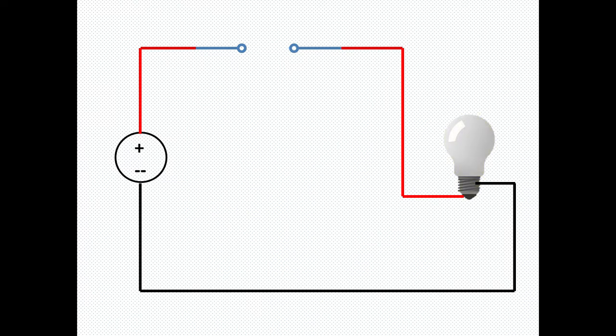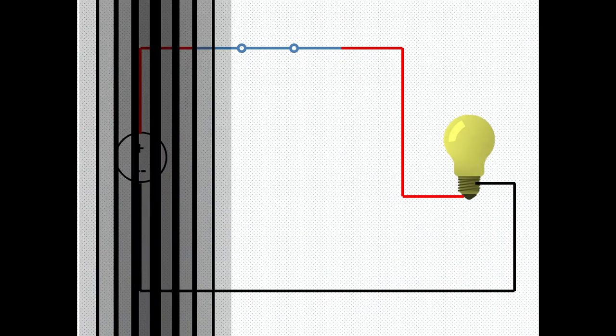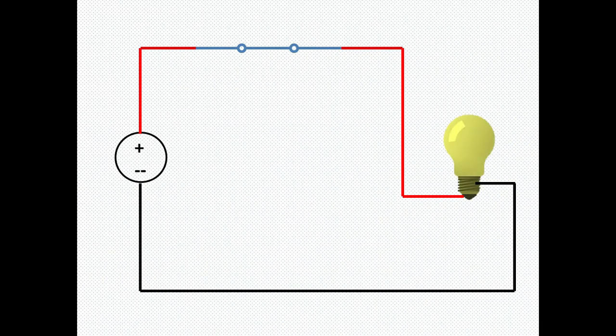At this speed of transition, one can clearly differentiate between the on state and the off state of the load. Let us increase the speed of the switching. As you can see, the lamp is also following the switching speed and it is turning on and off accordingly. At this stage also, one can easily distinguish between the on state and the off state, but it is relatively difficult to perceive. If we further increase the switching speed, then the turn on and turn off of the lamp load will also speed up, and it becomes more difficult to differentiate between the off and on states of the lamp.